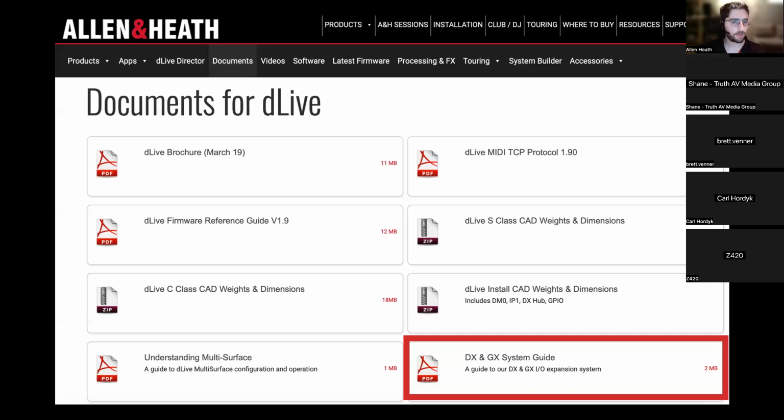Yeah, so if I understand, some people have the DX port on their console go to a standard, dumb layer 2 network switch, and you have multiple connection points for the same stage box, yes, that's totally fine. You can go from the DX port to a network switch, have that branch out to multiple pockets on stage, and then you can carry your DX168 around and connect it to any of those pockets. As long as you don't connect to 2 of those pockets simultaneously, then you're okay. You can't connect them in parallel. But if you just have multiple connection points and you're only using one at a time, then that's totally fine.